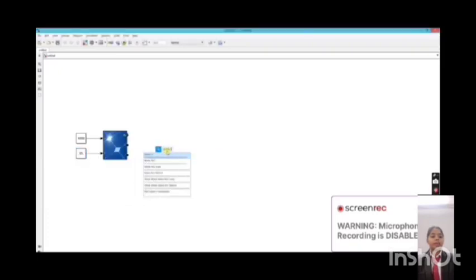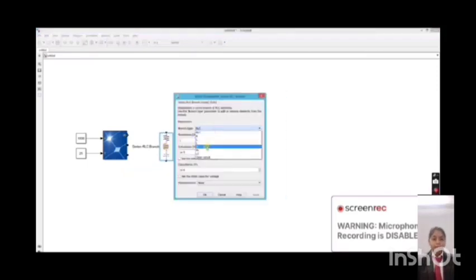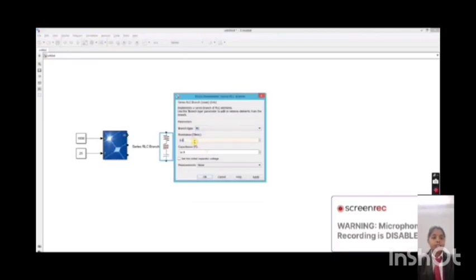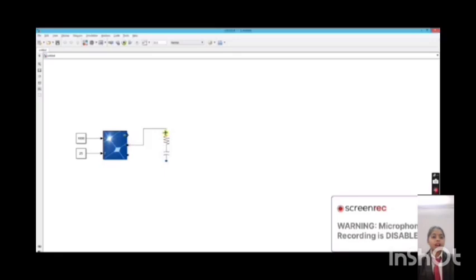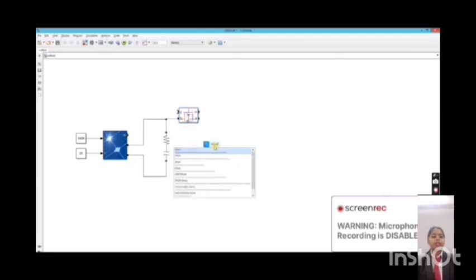Third is MPPT control design. Use the perturb and observe or incremental conductance algorithms. Measure the PV voltage and PV current from the solar panel. Calculate the maximum power point and generate the appropriate duty cycle for the boost converter. And fourth is the battery model.